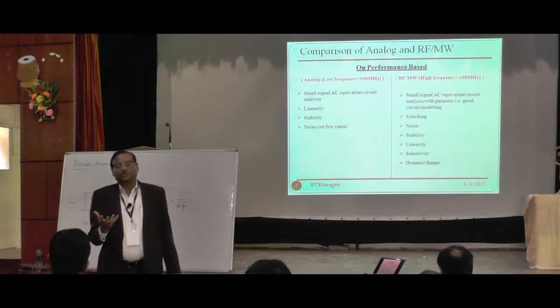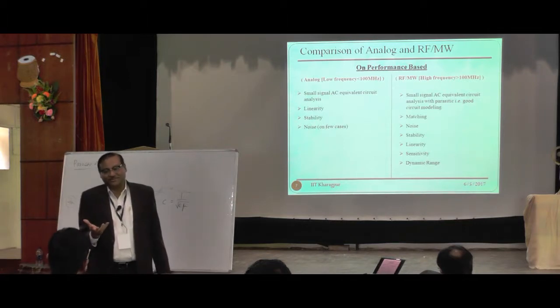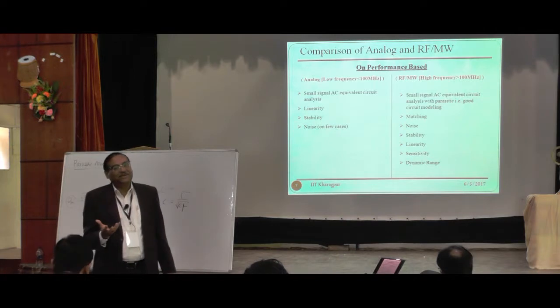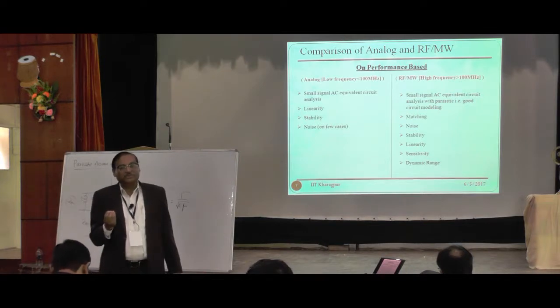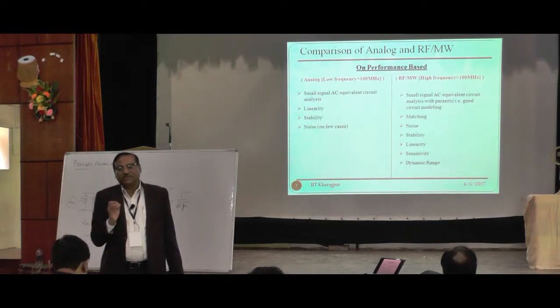Electron energy distribution is Maxwellian in characteristics. So that's why all your IV characteristics are exponential in nature. Is it clear? Only in the first-order approximation are you linearizing that form, which assumes that your input signal to the gate of the transistor is very, very small compared to the bias.